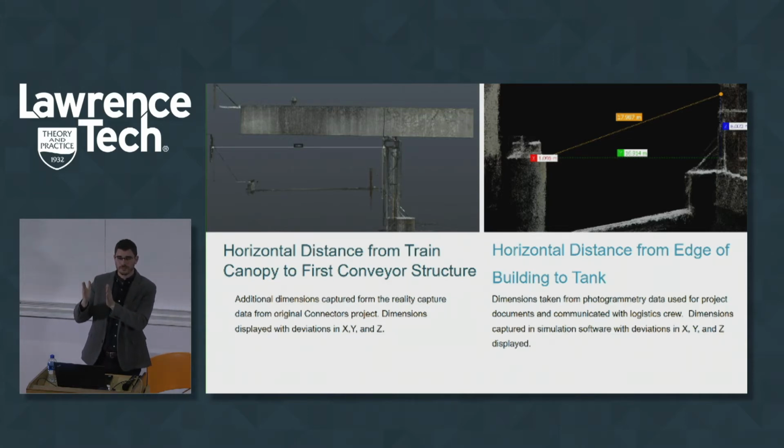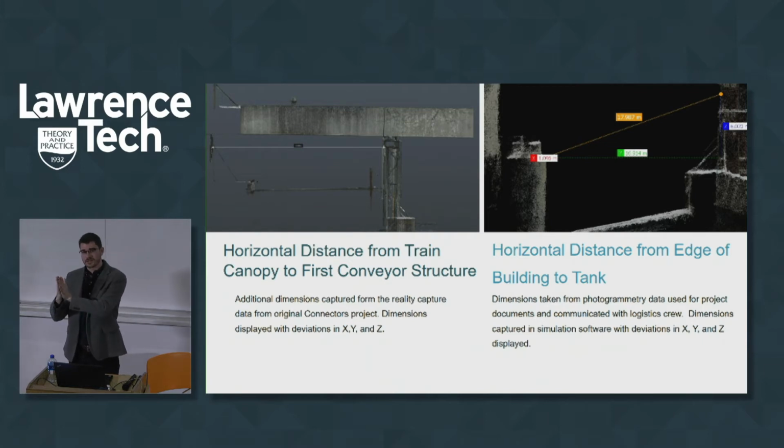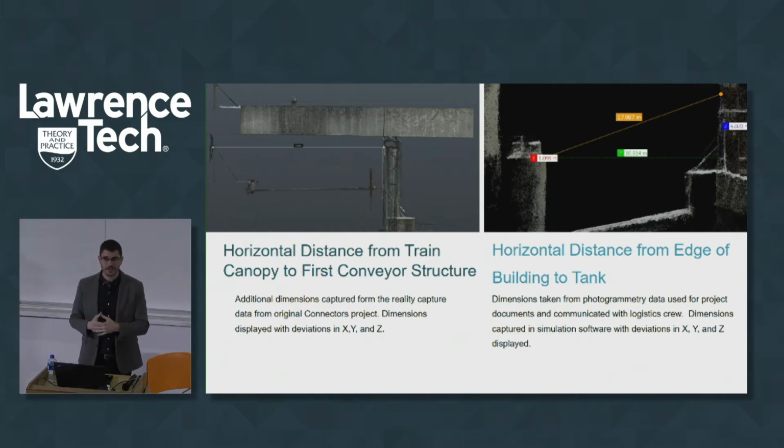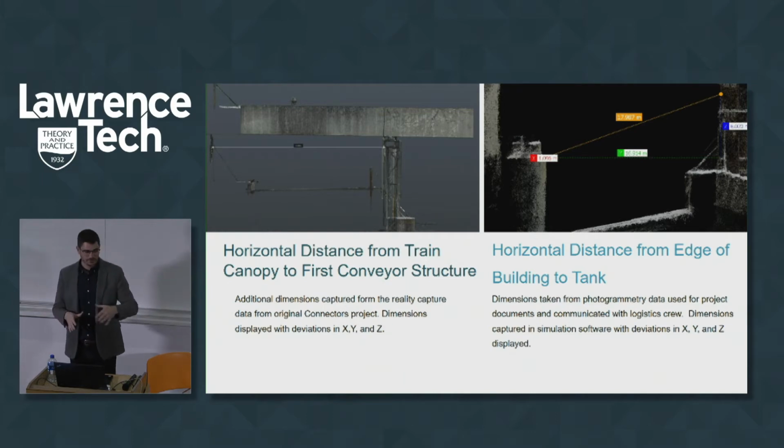So then we can measure back and say, okay, so that's where my crane has to be. So now I can position that to see, all right, how much space does that give me between conveyor structures and whatnot, and we can begin to simulate all the aspects of it. And on this project, as we began to simulate every different part of it, there were different issues with just transporting the assets into the site. With how big these things are, they required custom lowboys and different vertical clearance tracking and simulation on the actual site and getting it into the site.